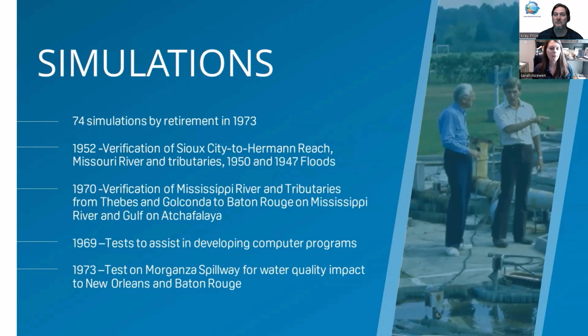They wanted to run what happens if we have coinciding large events on like the Red River or in the Ohio River Valley. How do we handle and manage the water in our river and tributary system along the main line? Because that's a big economic driver for the U.S. How do we maintain that? How do we operate that? When do we make decisions on floodways? So they used all these simulations to help not only inform levee heights and how those levee heights may negatively or positively affect people up and downstream, but also how to make decisions on operating of floodways.